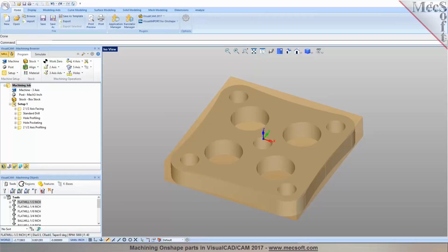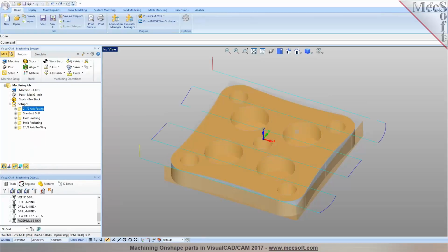Right. And you could specify, then it would go get the correct holes. You've got to manually make the tool selection, unless it loads the tool, whatever you have right in here. But then we can say select the geometries automatically. So this could be a spot drill operation for holes that are 1/4 inch all the way down to maybe 3/16 holes, right? So you can select holes of a certain size automatically and then apply the toolpath, rather than having to go and individually pick each of those holes.